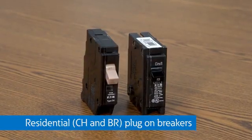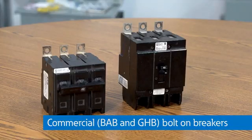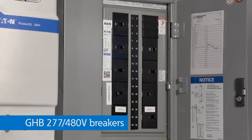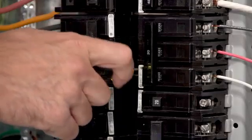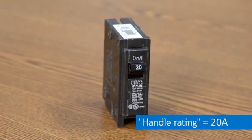Eaton's residential breakers are CH and BR plug-on breakers that physically plug onto the bus in the load center. Our commercial miniature breakers would look like these bolt-on BAB 120 or 208 volt breakers used in commercial or industrial panel boards, or these GHB breakers used on 480 volt lighting and control circuits. These require a bolted connection onto the bus in the load center or panel board. The size of the breaker is indicated by the handle rating, like this 20 amp breaker.